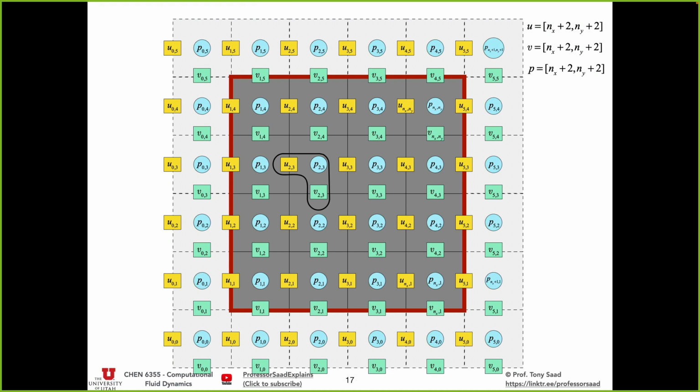So I decide to add ghost cells on the pressure, but also we will stagger the same way to the left, only to the left. So this ghost cell would stagger the u velocity to the left, so we'd have a u velocity over here. We're probably never going to use this. Maybe. But also on this control volume, we're going to stagger to the left. We will have a velocity here. This will be 0 if it's a wall. It will be some value if it's an inlet. Who cares? It's a variable. But I'm not going to place a velocity over here.